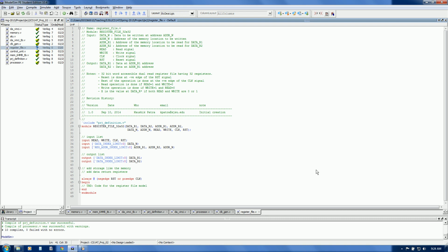Write at the register with their address. Okay, so register 1, write 1, register 2, write 2, register 32, write 32 there, and then for each of them in a for loop, read back the content, and the content returned must be the same as the address value, right? So register 1 will return a 1, register 2 will return 2, register 32 will return 32. So this is one simple test strategy.